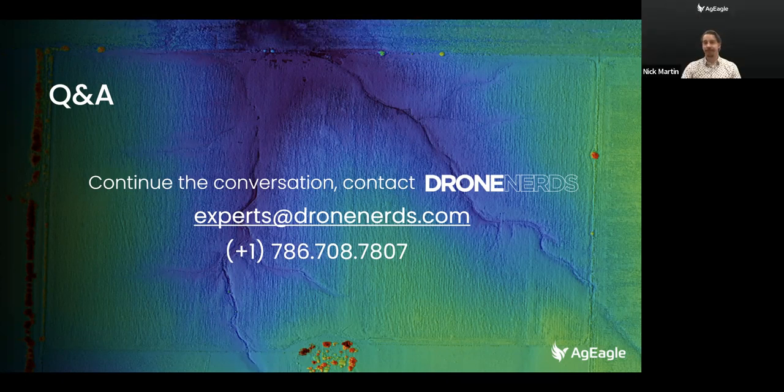Yeah. Do you recommend triggering by distance or speed with your sensors? Automatic triggering based on waypoints is what I like. MicaSense cameras have RTK compatibility. So we use a DJI piece called Skyport.